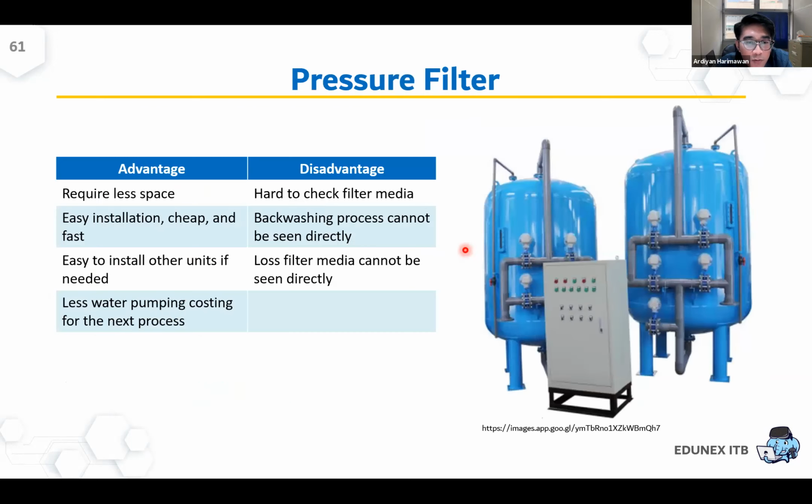And then we also have the pressure filter. These pressure filters basically use pressure to overcome the pressure drop that happens in the filtration process. But because it's pressurized, the outer container has to be in really good closed condition, because it has to sustain a certain pressure.